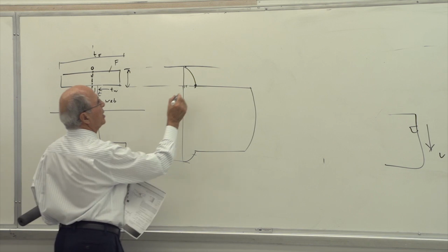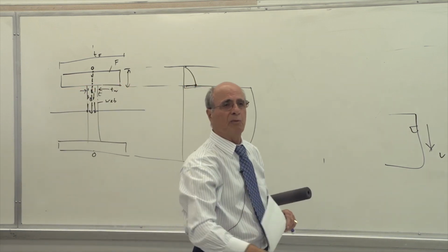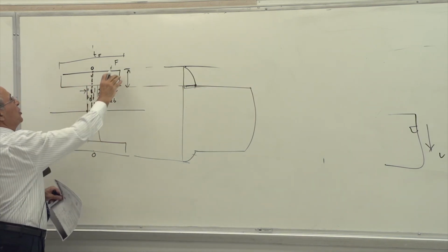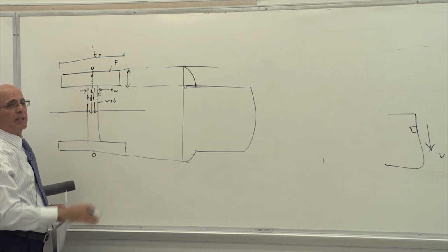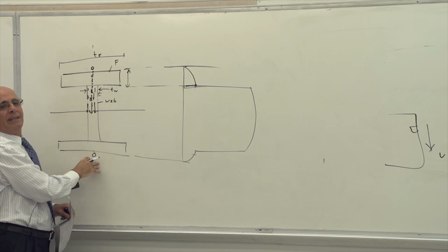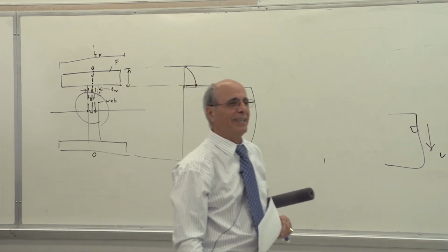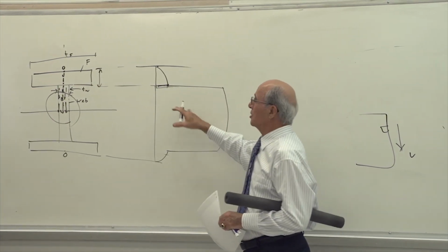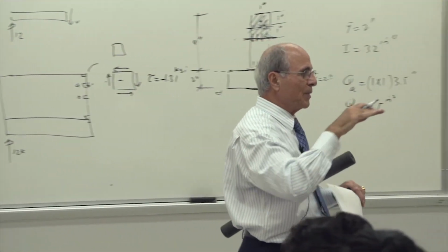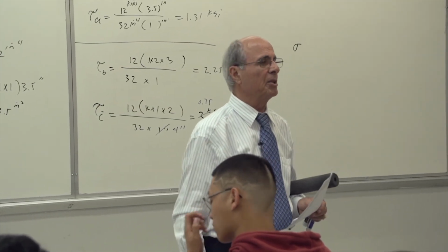But what is important here, like what we saw, is that there is a shift from a little one to a larger one. So in other words, remember what we designed this for? You designed this part, just for future reference, for the normal stresses, because normal stresses are higher here and here. Look at the shear stresses. The web is actually for the shear stresses, and the flanges are for normal stresses, combining the two. But you don't have to worry about it. These are extra information. Everybody understand what I'm saying?